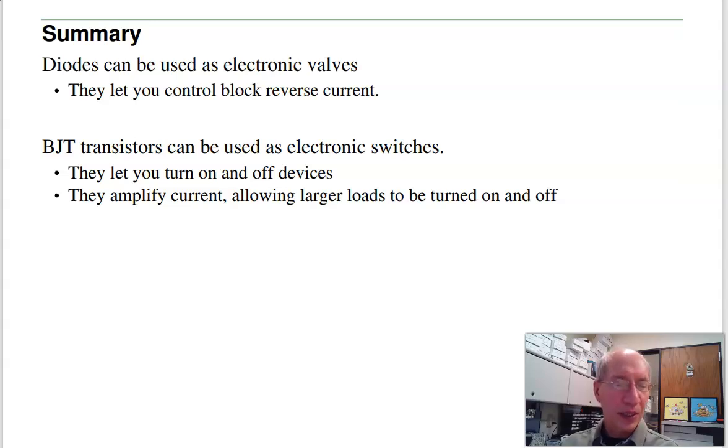I can take something wimpy, like a Pi Pico, run it through a transistor, and I have a Pi Pico capable of 12 milliamps, now capable of driving an LED at 20 milliamps, or a speaker, in this case at 12 times 100, 1.2 amps. Allowing me to take a kind of wimpy processor and drive a speaker at some power, make enough noise to annoy your friends and neighbors. And that's week number 5 for ECE 401, Senior Design 1.